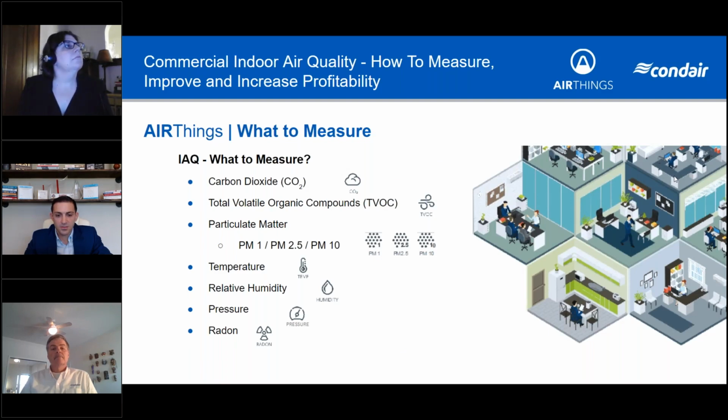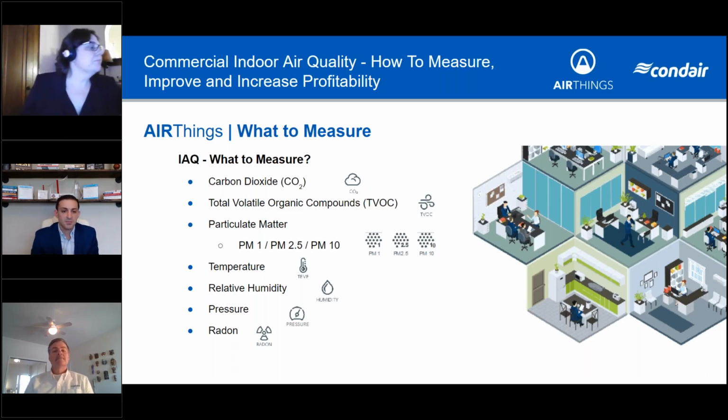All right, excellent. We'll go through some relatively high level on this slide. What are some of those parameters? I alluded to some of them, but CO2. CO2 is very important for cognitive performance, making sure that we have proper ventilation. If I relate it to the ASHRAE standards, I believe historically it has been 750 parts per million over your outside air. Of course, your outside air fluctuates where you are, but it really is a powerful indication of how well you are turning over that building.